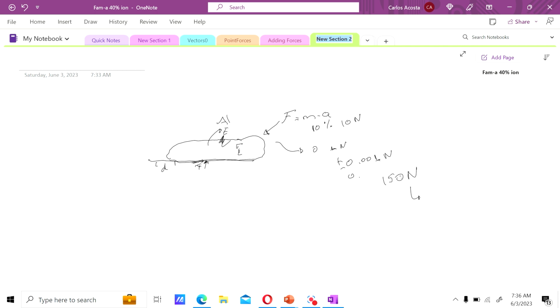If not everything was the same, it will be maybe 151 or 148, but it will be very close to 150 because your sensor has an accuracy of 0.001 Newton. And the drift or the offset is just because of things that changed during the experiment that you couldn't control, like wind speed or air humidity, or if it started to rain, whatever. But the sensor itself has to be very accurate.